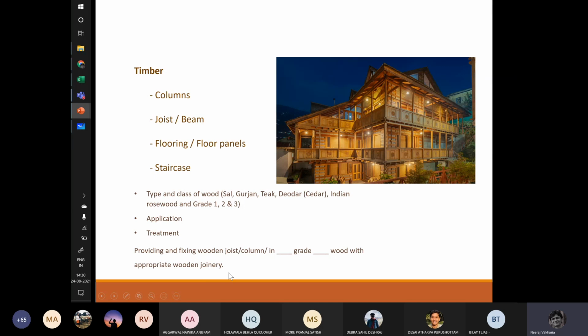Now, if the joinery is something customized, then you might have to use those specific words. If you are using steel plates and steel gusset plates, which people also use sometimes to make portal frames out of wood, so the steel joinery is also used. If you're going to use that, then you have to mention how they are going to get connected, how they're going to get erected, and how they're going to connect.